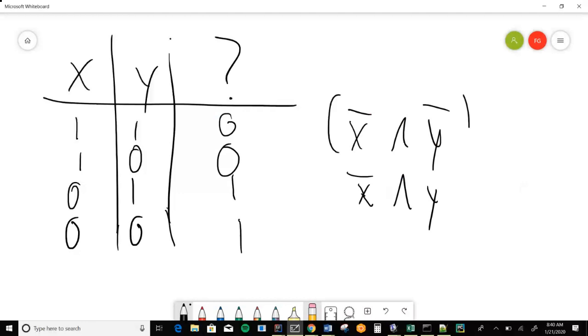But now here's the cool part. I can connect these with an or. And now I have mechanically synthesized a digital circuit from an arbitrary truth table using and, or, and not. This isn't, of course, like a full-blown mathematical proof or whatever, but it illustrates the concept of logical completeness of digital circuit operators, right?